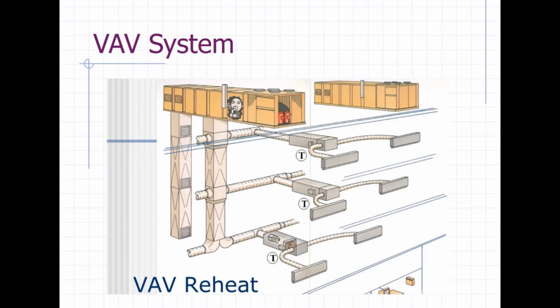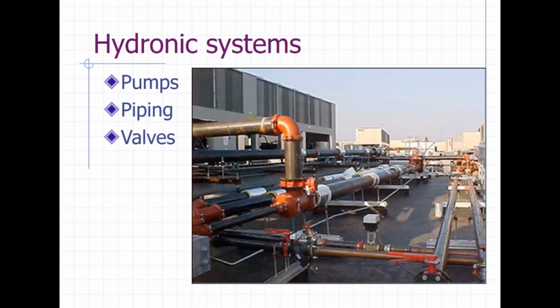So these are typically energy saving features. As those dampers back off, instead of similar to a VVT system where you would back up and bypass damper, as the dampers start to close off, the pressure inside the ductwork starts to build up, and then your fan ramps down with a VFD. So your fan basically modulates off of duct pressure based upon what the zone dampers are doing within the system.